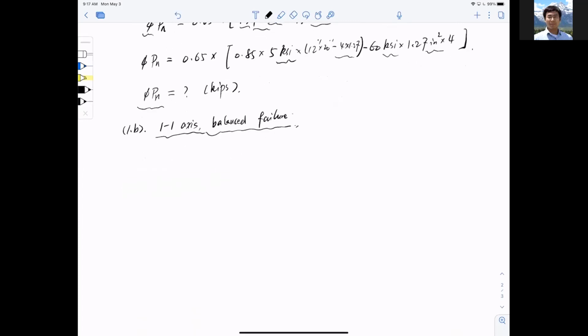Again, let me take a look at the diagram, right? We know that from this right here, the axial force versus bending moment loading, and the curve looks like this and turns back here. Okay, so at the balanced failure, we know that is right here at the knob, right, and here at the peak here. And then we say that the strain at the balanced failure equals the yielding strain for grade 60, 0.00207. That is the input. That is the given information.